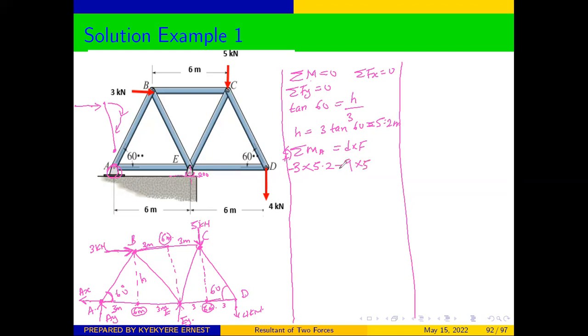But why are we getting the negative? Because if the force is applied in this direction, and this is the perpendicular distance, A, then we can see that this force is going to rotate this beam in this direction, which is also clockwise, and therefore it will be negative.